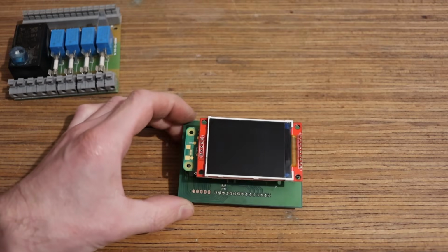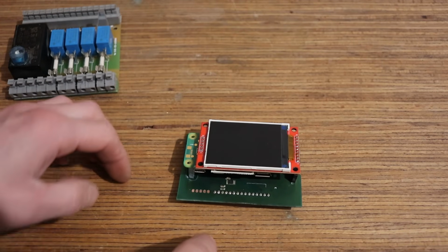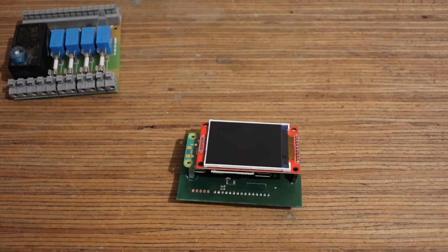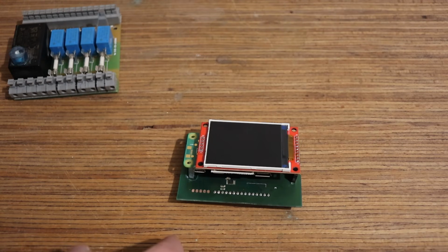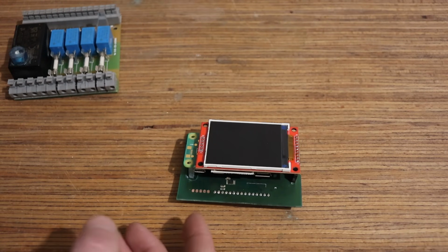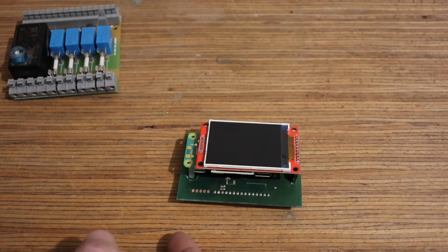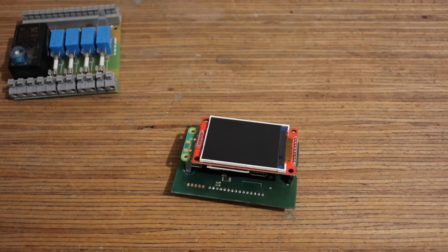There are some things I would like to change for future revisions. For example, the keyboard: I was thinking, okay, we'll have 4 keys, up, down, left, right, and that would be enough for a basic user interface. Then I was thinking, well, actually having a rotary encoder would be much nicer. And for a rotary encoder, you really want to connect to the I2C bus and have a dedicated microcontroller for it. Something really tiny. I'm not sure what I would use, but this could be integrated on this board easily, so I would probably do that.